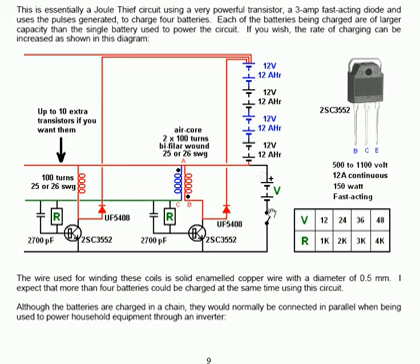Again, it's the same dual-T circuit, 2 strands of wire, each with 100 turns side by side, wound round an air core former. By air core, that just means it doesn't have anything in it. It's an empty tube that's been used to wrap the turns of wire around.